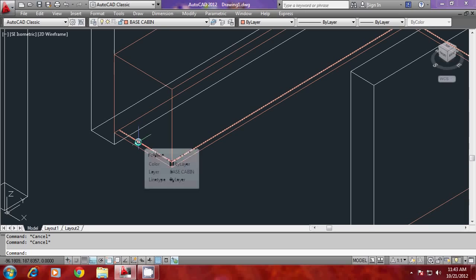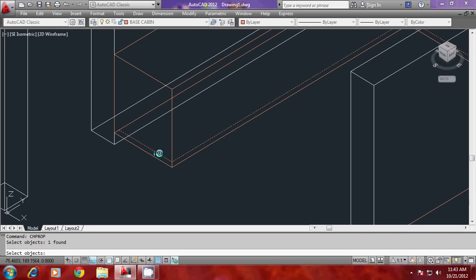The best method to give a thickness for the skirting is using a command called change property, because you know the change property command will let you generate a surface out of a profile. So I give change property and I've selected the profile. Then it will ask you which property to change. I'll select thickness here, so I'll give thickness. So it will ask you for the thickness. Thickness is -10 because it has to be given in the negative as a direction.